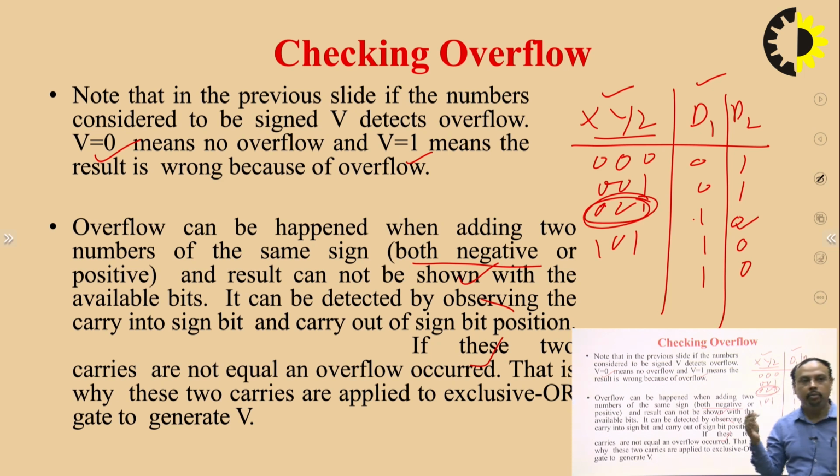In this way, we have the truth table. With the help of the truth table, we have to find out the minterms involved in the corresponding output, and minimize the minterms or the gates required for implementing that circuit with the help of K-map techniques and Boolean algebra techniques.